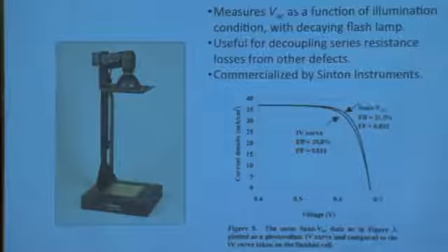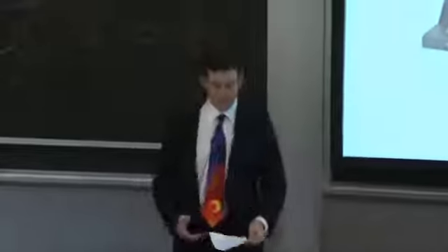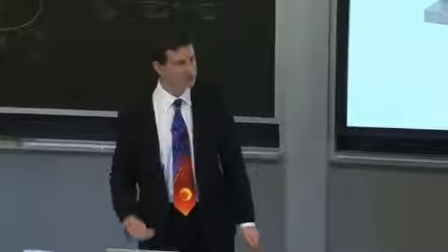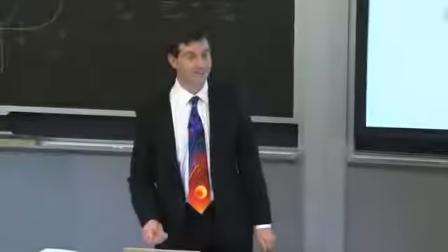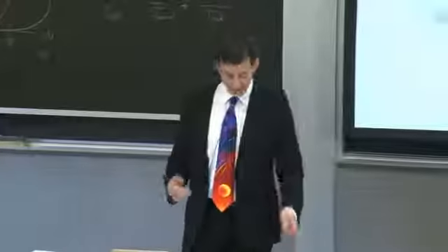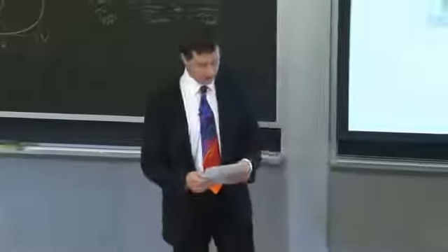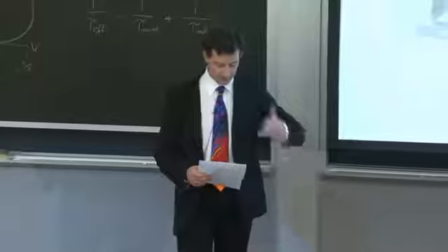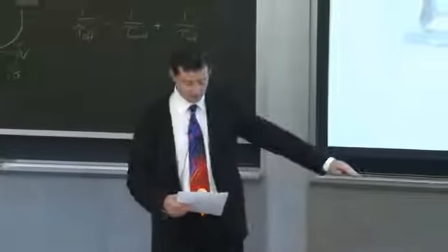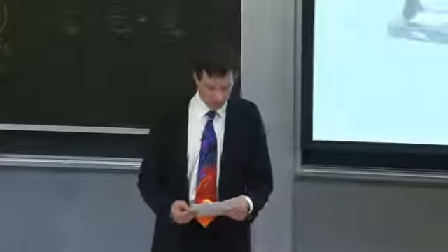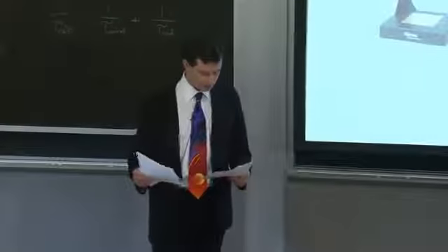There's a natural log. Yes, this is what Joe showed to you yesterday or on Thursday in class, is how the voltage output of a solar cell varies by illumination intensity. Right? So there's a logarithmic dependence there. So that's why you take the log of the exponentially decaying light intensity and you obtain a linear relation. That's the open circuit voltage decline as a function of time.